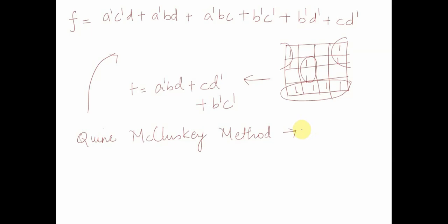So basically for this, what we need is a method to eliminate basic redundant terms which are present in the Quine-McCluskey solution, right? For this, in the Quine-McCluskey method, we will do something called a prime implicant chart, PI chart. The prime implicant chart is the second part of the Quine-McCluskey procedure. It is used to select a minimum set of prime implicants. Similar to the Karnaugh map, we select the essential prime implicants and then we select enough prime implicants to cover all the minterms of the function. So I hope this is clear, right?